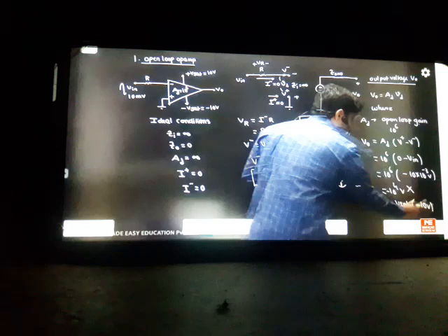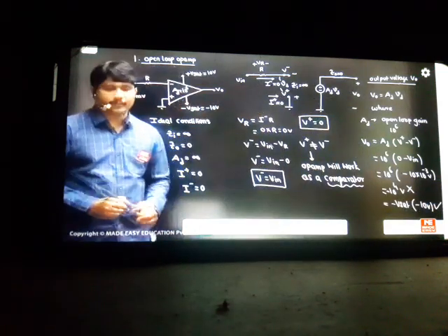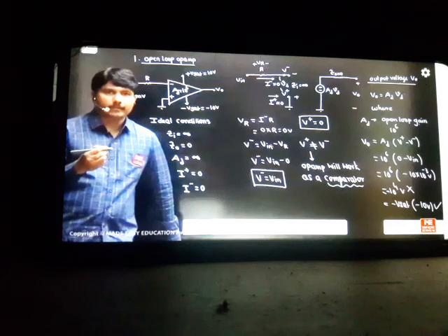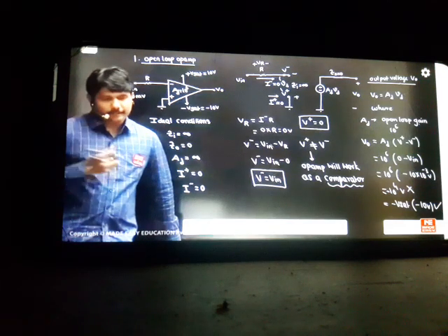If it comes in the negative, same approach. So I think your answer should be minus V saturation. So the answer is minus V saturation. Minus V saturation is minus 10 volts. So this is the wrong answer, and this is the correct answer. Don't blindly write minus 10 volts, because op-amps cannot go beyond minus 10 volts. It can only go up to minus 10 volts because op-amps cannot work beyond the battery limits. That is the concept we got in the graphical analysis.